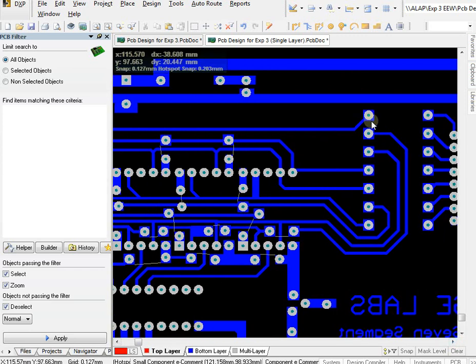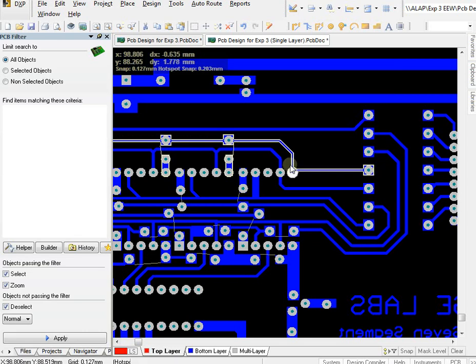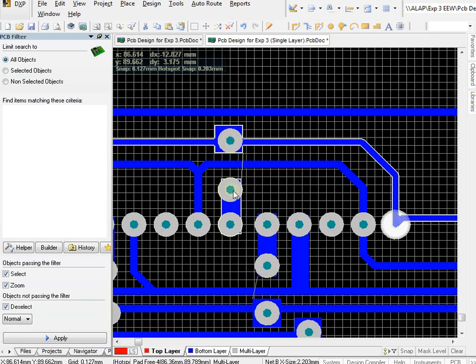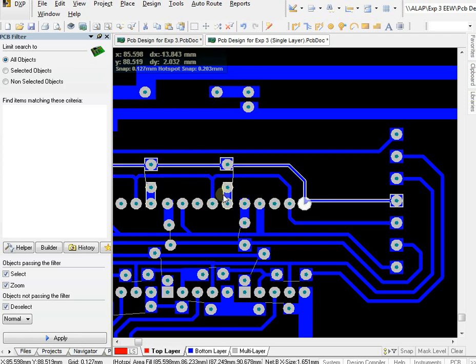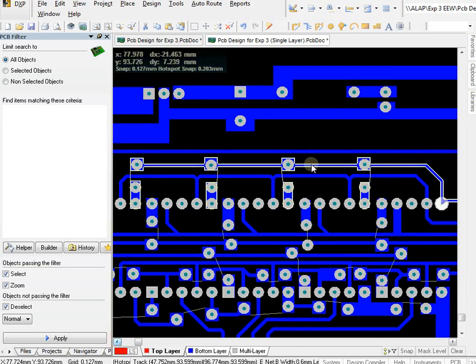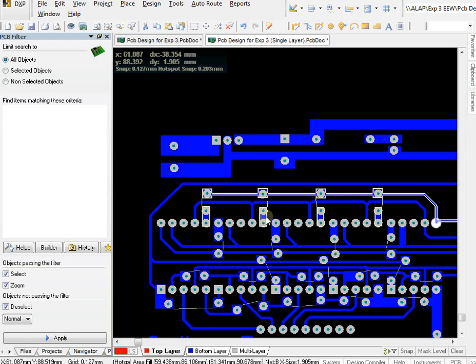From the resistance, you can see this segment. What is this segment? This is B. B is connected with this pin, and then certainly it has to be connected to this pin. So what I have done, I have taken the wire, taken up till this point, added a pad, added another pad over there, and I can put a jumper wire. And you can see there is a transparent line over there, in fact a white line over there. So this is actually showing me that there is going to be a jumper wire. Similarly, that wire is flowing up till the very end. So all the 5, 7 segment B's here, 1, 2, 3, 4, and the 5th is already connected.